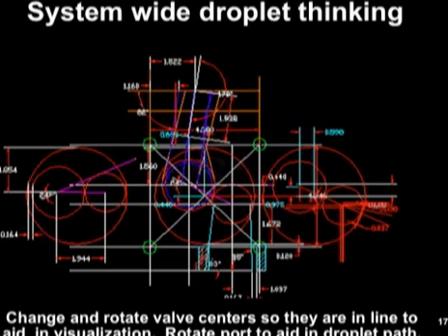compared to where we've gone over the years. If I was to go all the way back to that slide where the port was placed differently over the cylinder, as time has gone on, we have gone from being in the back to middle to forward, like the engine in a Ford. If you look at it relative to putting the valve centers on line, the valve center has moved way away from the bore now. When I do this, I also can begin to design how I am going to enter the cylinder for the in-cylinder motion and droplet path. So here, I can make all the different drawings before I ever decide that I want to make the engine.